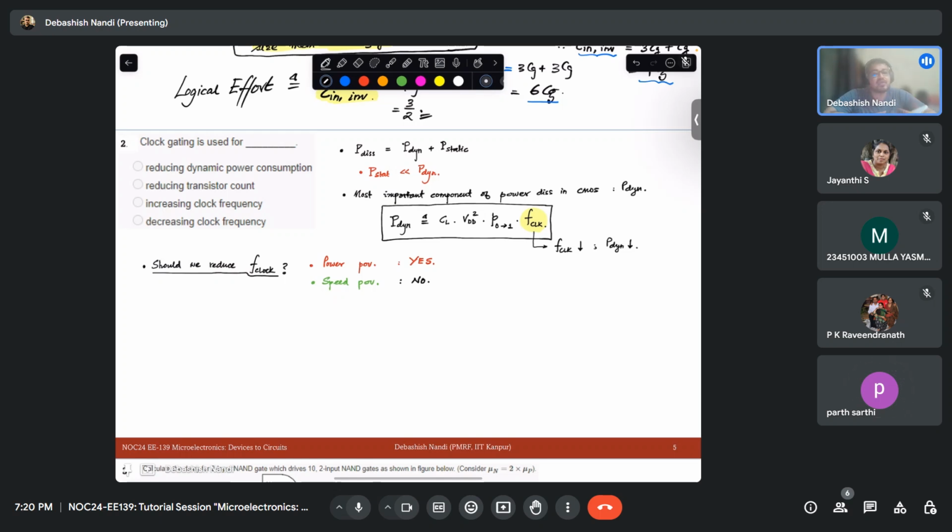So how to get away with these things? The way to get away with this is to use the clock only when instructions are carried out or circuits are in operation. If it is not in operation, remove the clock. So how do we do that?